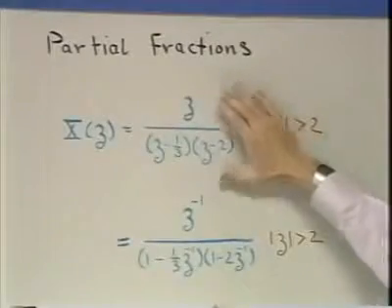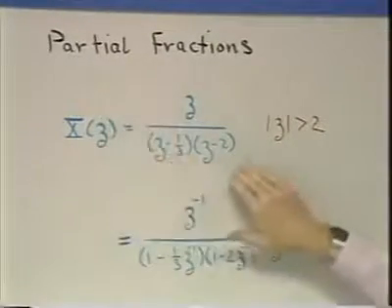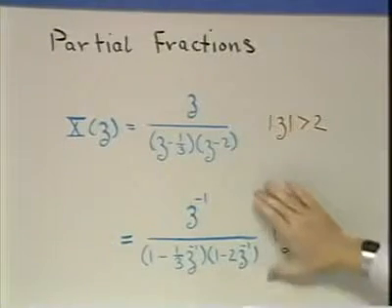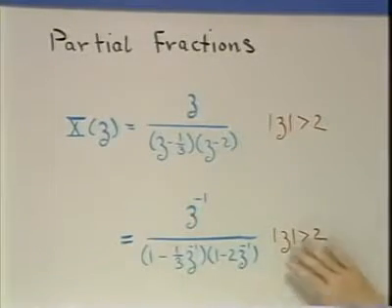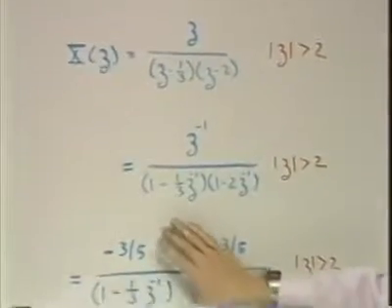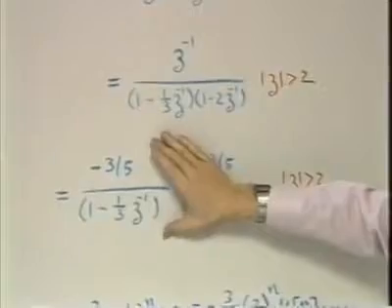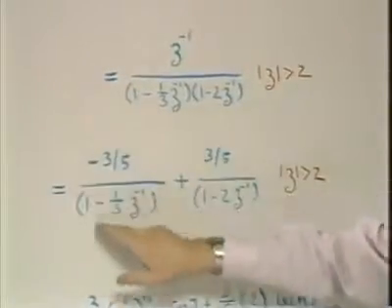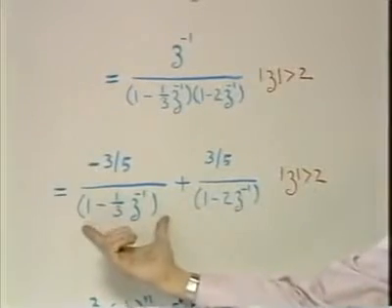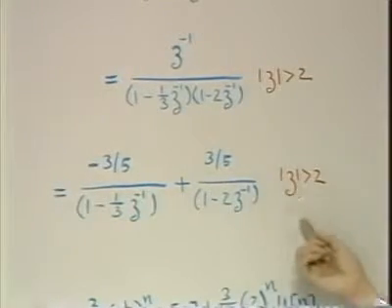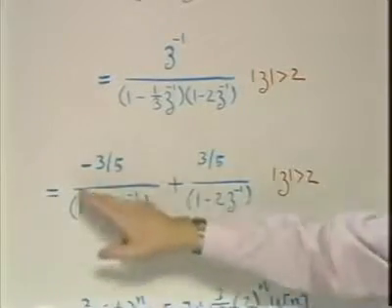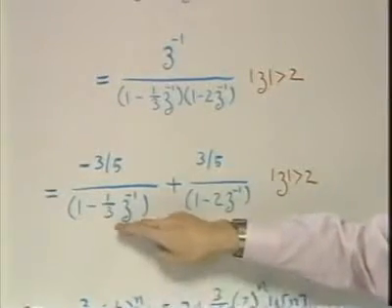So if we had a z transform as I indicate here, and if we expand it out in a partial fraction expansion, then we can recognize, as we did in a similar style with the Laplace transform, that each term, together with the identified region of convergence, corresponds to an exponential factor.